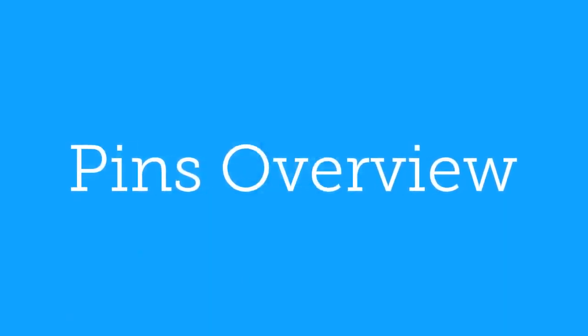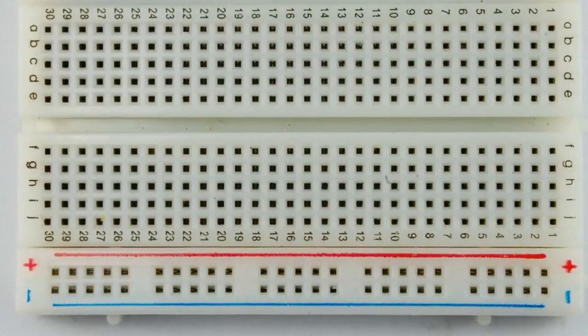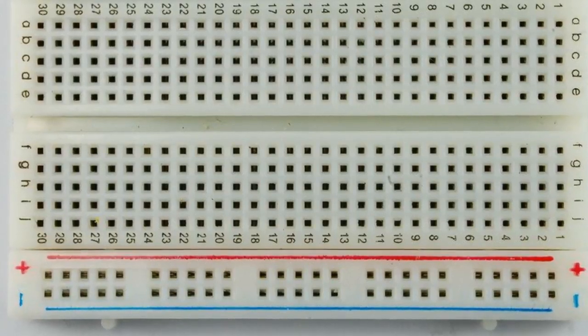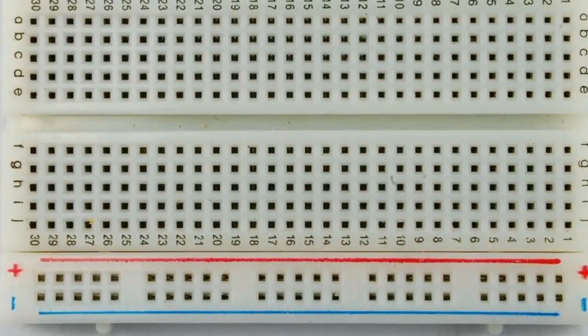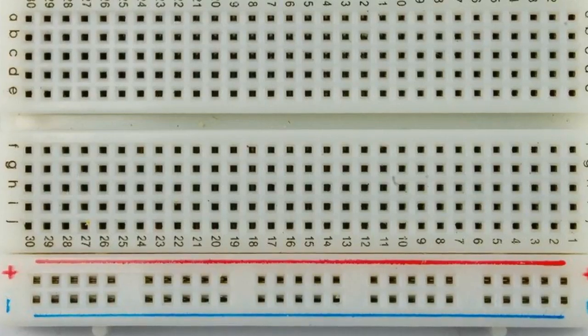Pins overview. The breadboard is where most wiring will take place. Running power through the breadboard to complete circuits involves plugging a wire from the 5-volt pin on the breadboard into the positive column labeled with a plus sign, and connecting the end of the last wire of your circuit into the ground pin on the Arduino or into the negative column labeled with a minus sign.